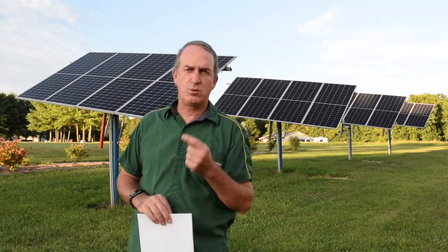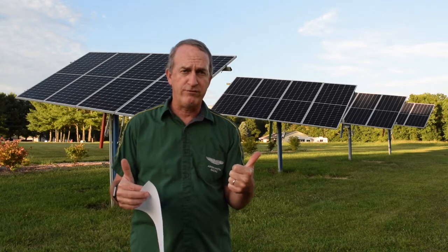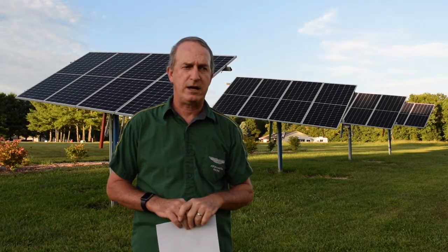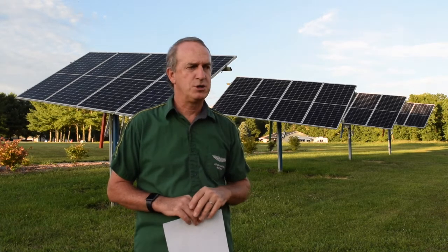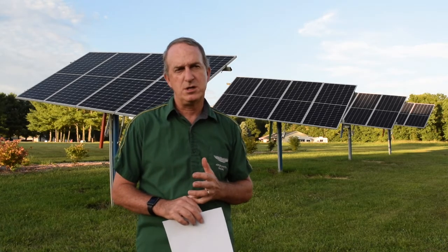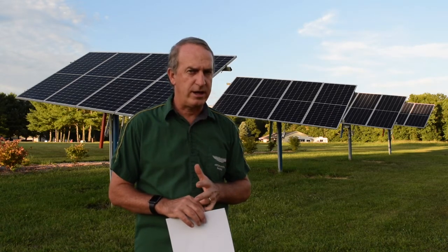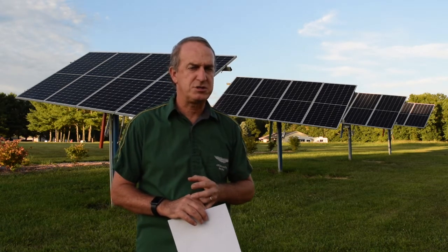If all the panels are wired up on a Sunny Boy system and you put your fingers on there, you've got about 400 volts DC, and that gets to be dangerous. So the optimizer system from SolarEdge is a little bit safer in my personal opinion, and it's clever, and it maximizes the amount of electricity.